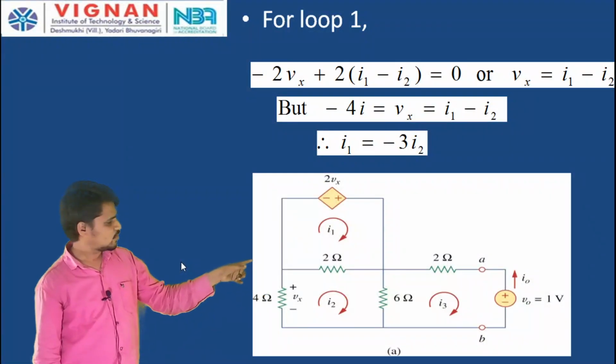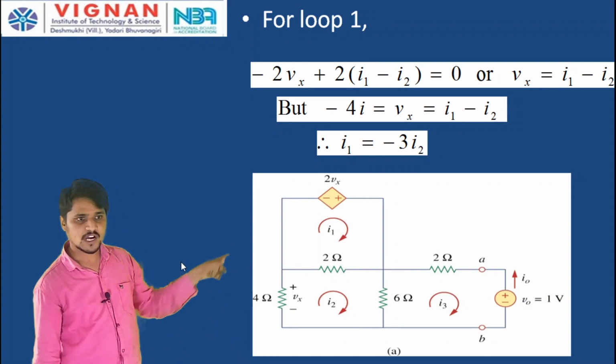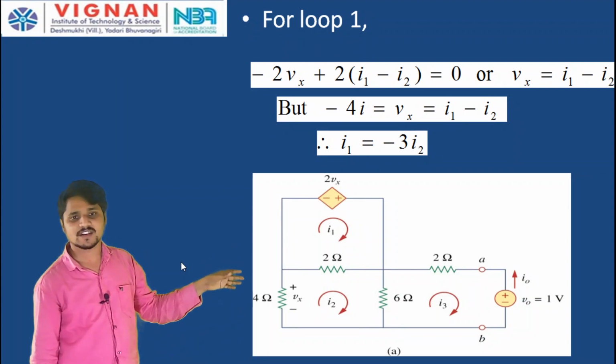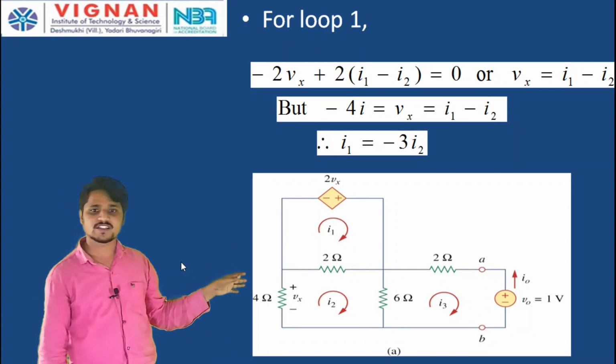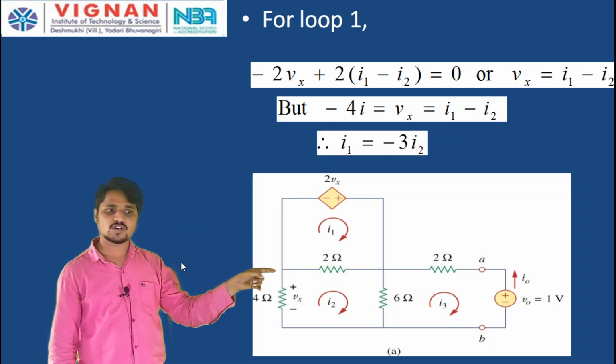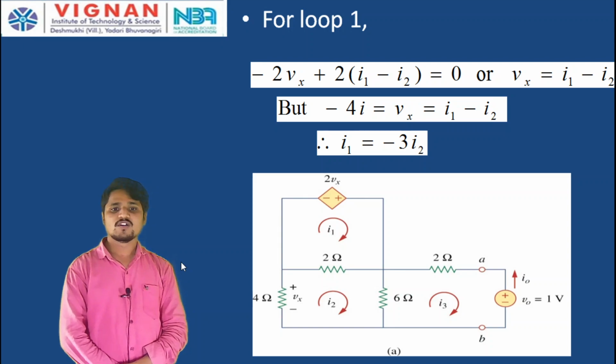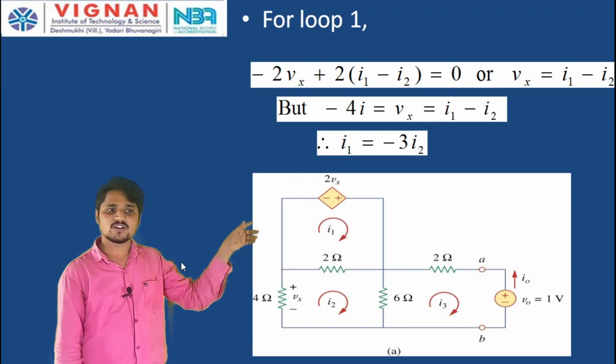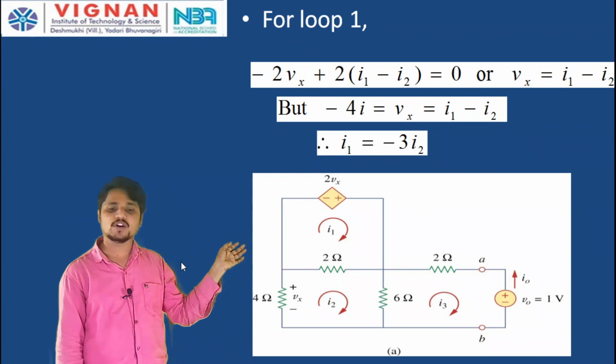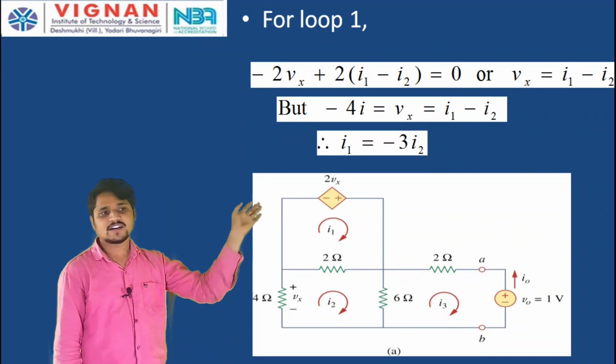So, now I have open circuited this current source, therefore, I have eliminated, killed the source. Now, only this circuit remains. Now, apply the 1 volt voltage source across the AB terminals. Now, first apply the Kirchhoff voltage law in mesh 1. I am using the mesh analysis principle. So, let us assume all the currents are clockwise.